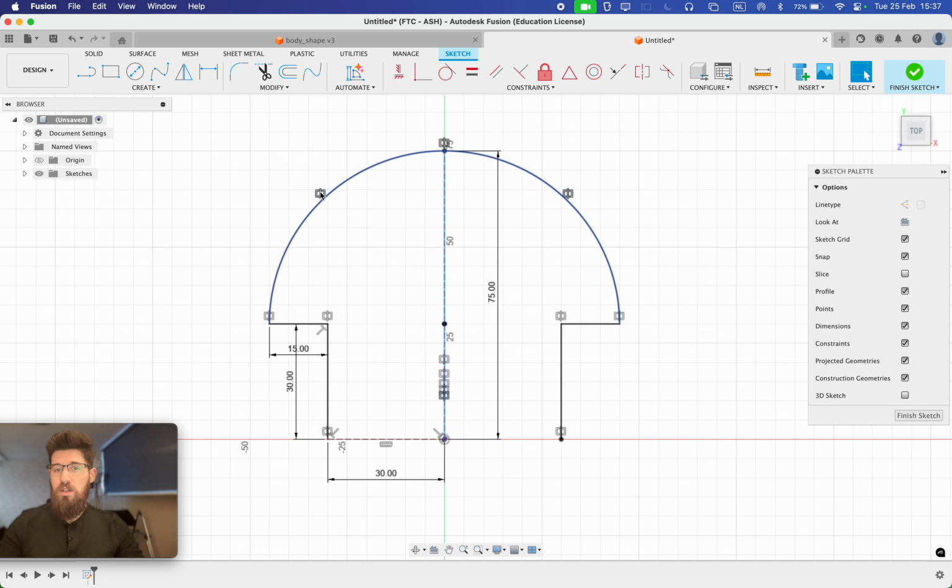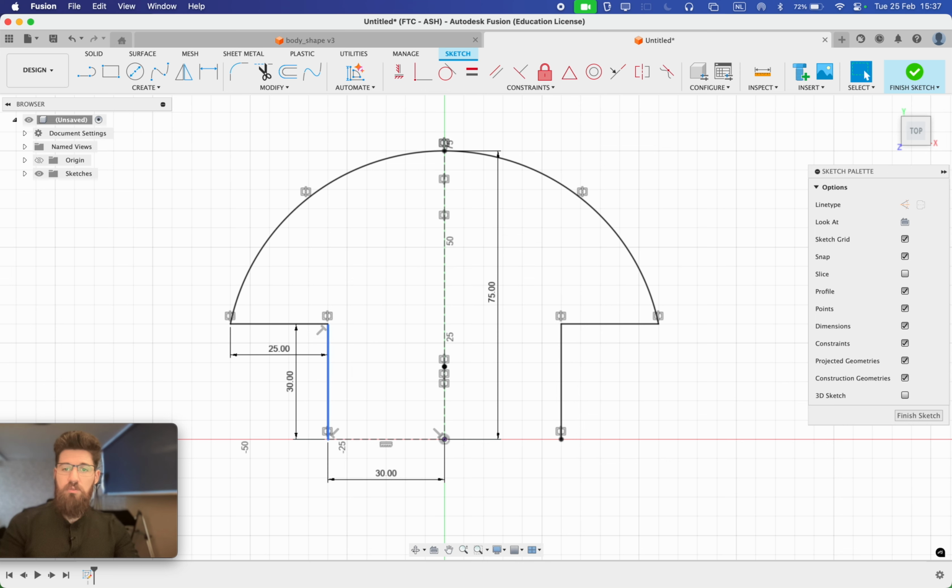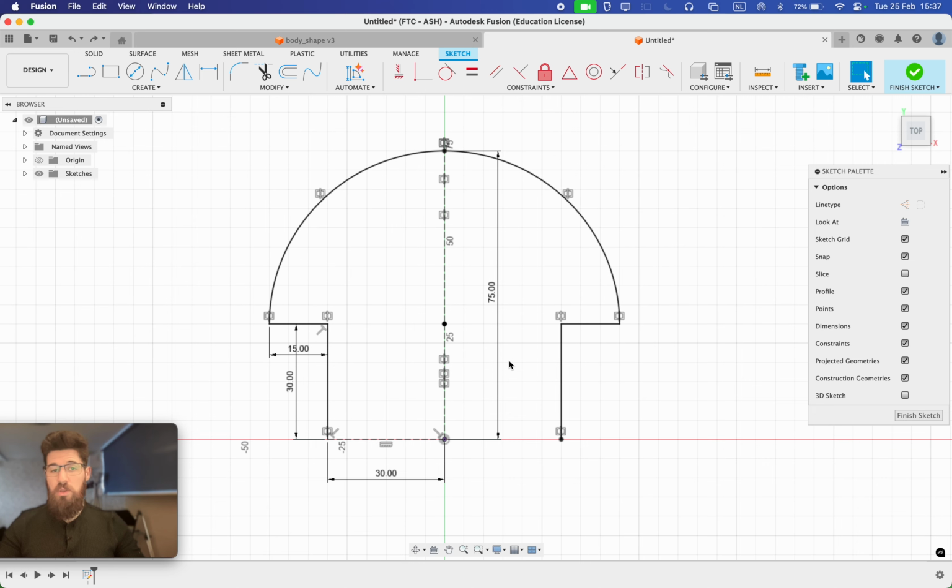You'll also notice that we have these new constraint points added, and these constraints are called symmetry constraints. They look like a little window, yeah? So when I hover over one, we can see which 2 parts are symmetrical with one another. So if I were to change one of these dimensions to say make this one 25, you'll notice that the other side also changed because as we mirrored it, it's going to try to keep it symmetrical.